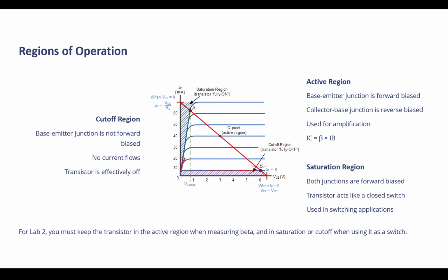Now, honestly, I don't know why they did that, but the naming of the regions is different. The part where we have linear or semi-linear behavior, when the current changes based on the voltage between the collector and emitter, we now call the saturation region here in BJT.